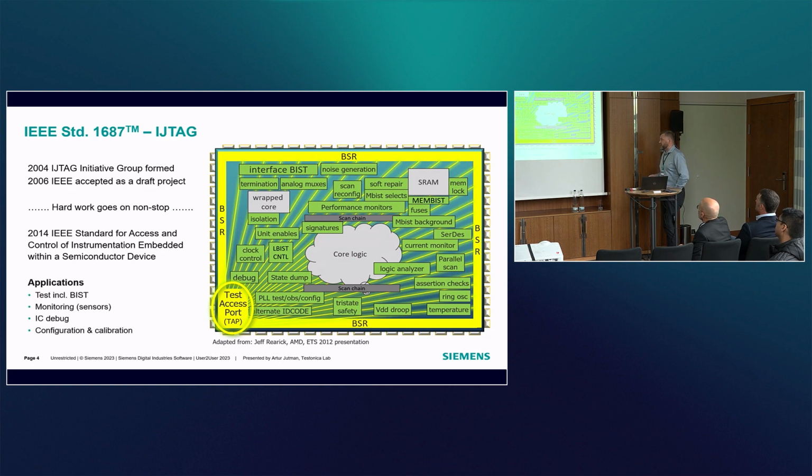For applications, of course, testing, including built-in self-tests and scan chains, also monitoring, even in-field monitoring is being actively added these days, in-system monitoring, IC debug, configuration, calibration, and also some of those instruments could be used for system level test beyond the chip.